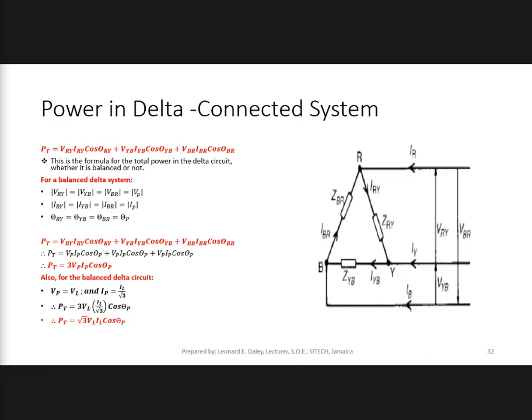Later on when we get down to transformers, and if you could do drives too, you will see machines are rated in terms of their apparent power, right? And how much you can actually get out of them is going to be dependent on the power factor at which they are operating. So if it is a purely resistive load, then the power factor is unity, and whatever you put in, you will get out.